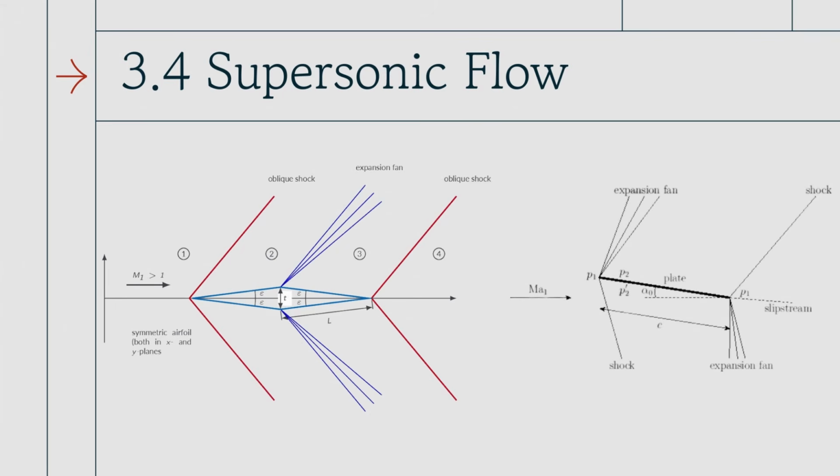Obviously, the shockwave is quite extreme, in that if you get a shockwave interacting with your vehicle, it can cause a lot of heating in that specific area. There were a lot of experimental vehicles in the 70s, 80s, and 90s where these shocks collided with other aspects of the vehicle and burned holes straight through parts of it.